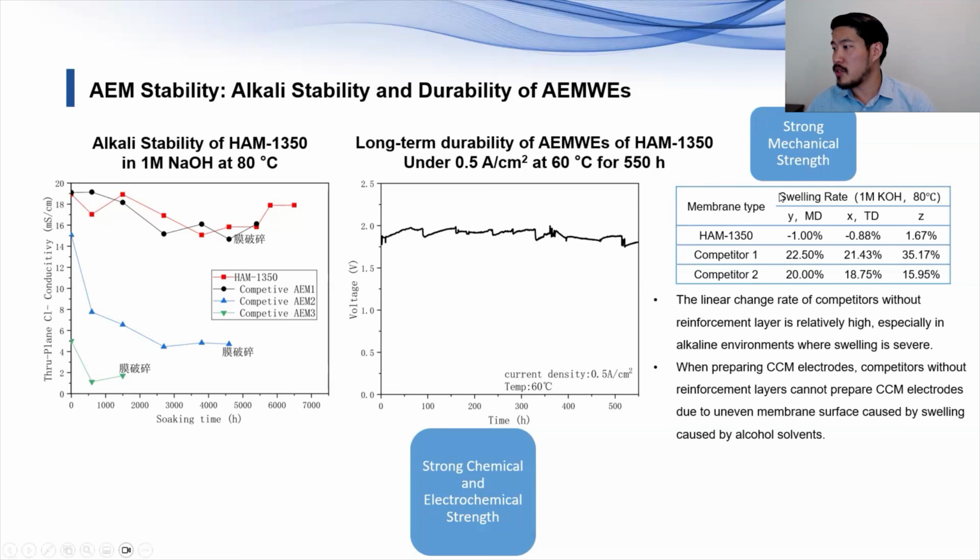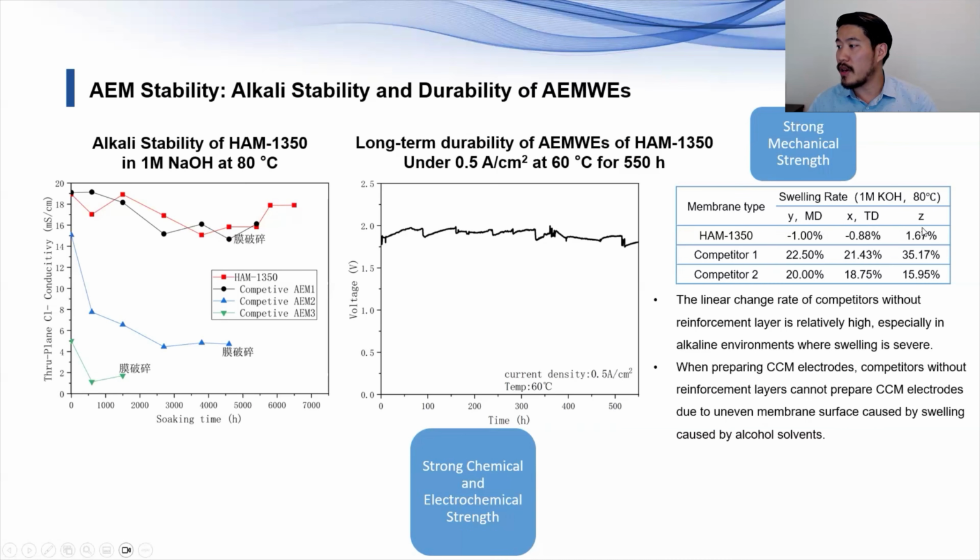And then on the right, there's the swelling rate as well. Some membranes, depending on how they're made, may swell a lot and get thicker, which affects how you're going to put it in. Sometimes you have to activate the membrane, swell it up. With ours, we tried to make it so that you don't have to do that. The swelling rate is very, very minimal, as you can see here with our anion exchange membranes. Other competitors make it differently, and we just want to show that theirs does swell. Whichever product you're using, you want to know how to activate it beforehand, because that's where some customers may run into issues.